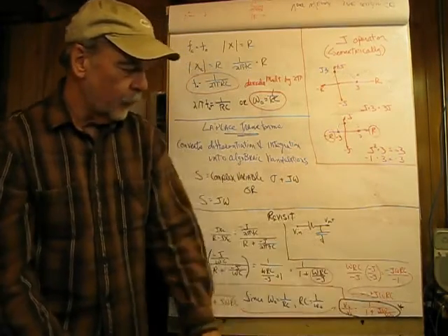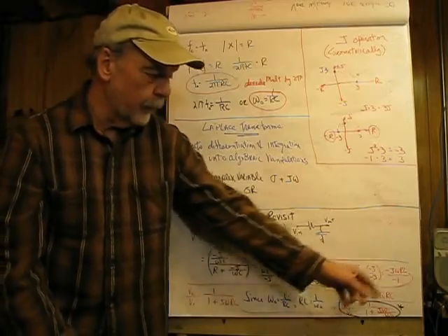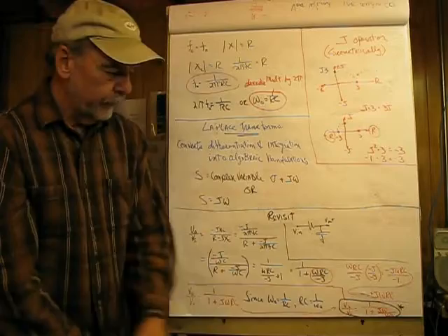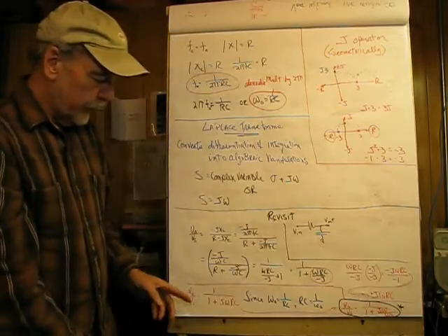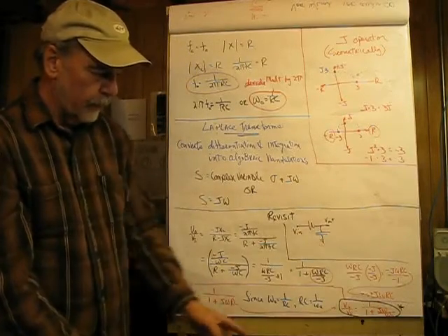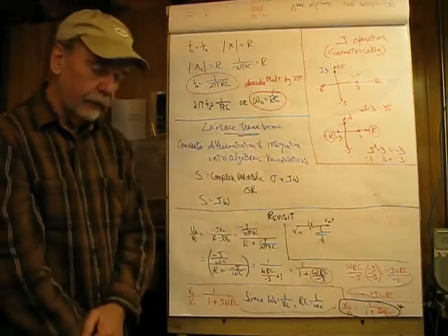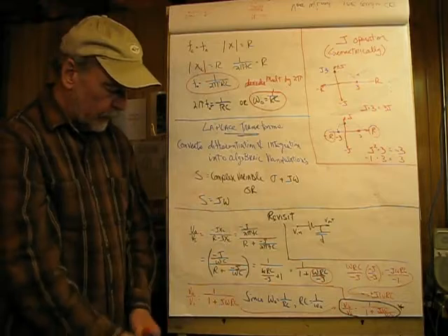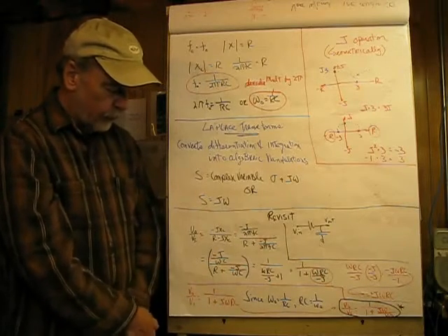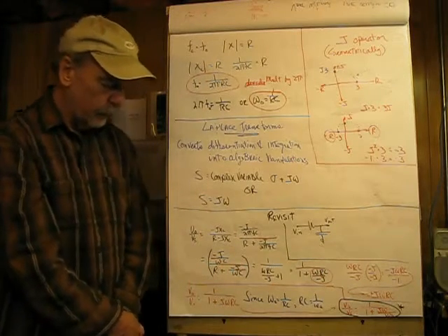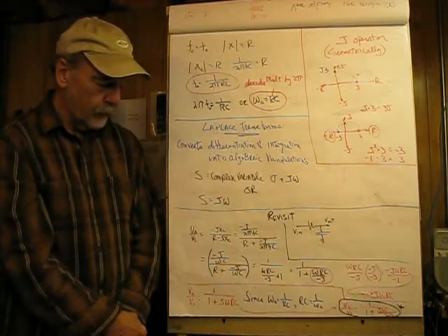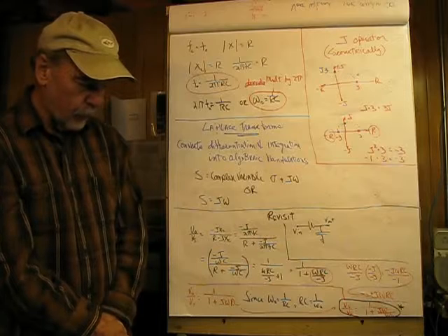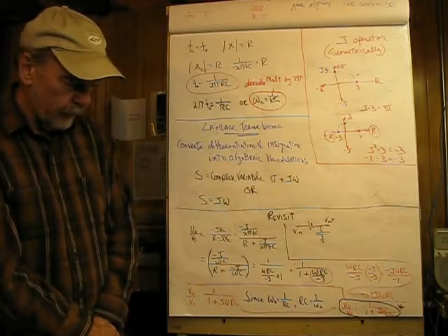And in the numerator now we have our negative j operator sitting in front of omega RC. So, in combining this, if we come back to here, we have a negative divided by a negative, which gives us the answer we're searching for: the ratio of V out over V in is equal to 1 divided by 1 plus j omega RC. So that's getting set up for the form that we want to use here.